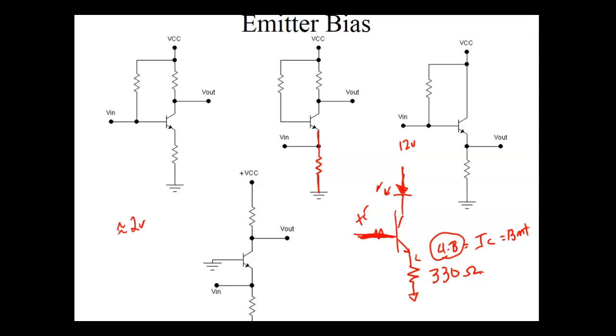But it doesn't make any difference, because with that resistor right here, I set my current at 13 milliamps. I don't care if it's red, I don't care if it's green, I don't care if it's blue. Well, what would happen if I come up and put another LED right there? Oh, now notice the arrow down. Oh, I'm sorry, I didn't put the symbol.